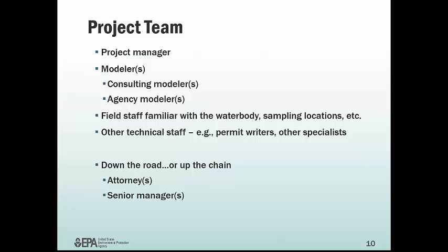I think of a situation where we're looking at a river and we're particularly interested in dissolved oxygen, for example, and your monitoring shows that there's consistent flows in the river, and then suddenly those flows drop off significantly, and right around that area you see very low values for DO. And you might say to yourself, well, what's going on right there? And you consult your field staff, and they say, oh, yeah, there's a wetland nearby.